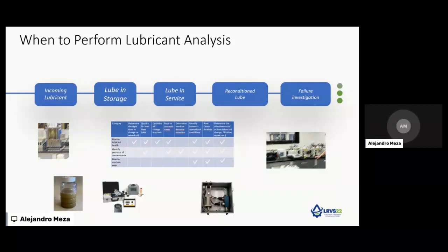We have, first of all, the categories of oil analysis, the goals that we are looking for in oil analysis, that concept in the context of the lubricant life cycle, and the resources we have: routine oil analysis, inspections, field test kits, online monitoring, advanced oil analysis, advanced grease analysis. We have huge resources to maximize the detectability of normal and abnormal parameters happening in the lubricant.